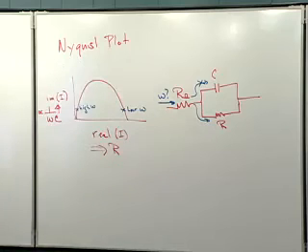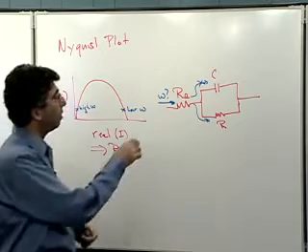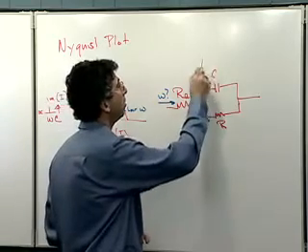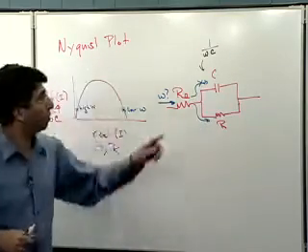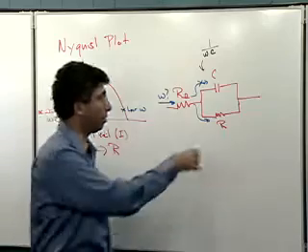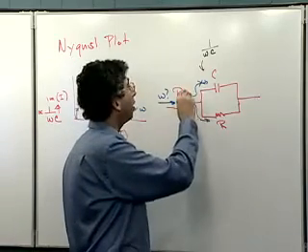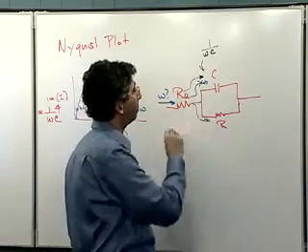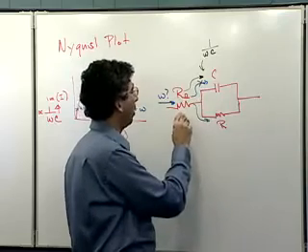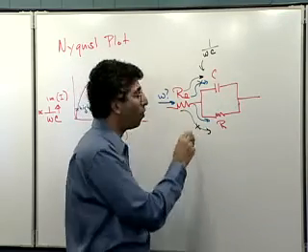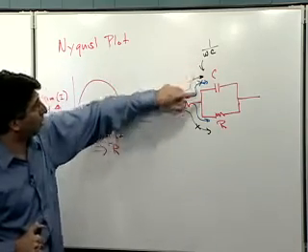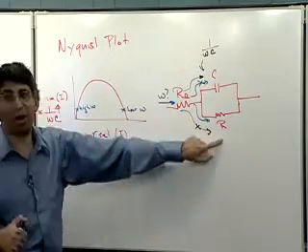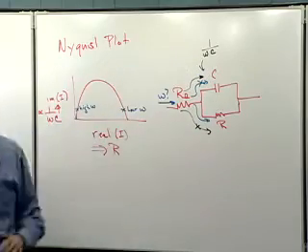And therefore, this is a high impedance path, and all of the current will flow through the resistor as a result. On the other hand, as I change my frequency, then at some point, since this goes as 1 over omega C, the impedance here becomes lower than the resistance over here, and there's some magic frequency where I start passing everything through this, and in that case, nothing will go through here. And of course, there's a set of frequencies where 1 over omega C and R are pretty comparable, and I have current going through both of those.